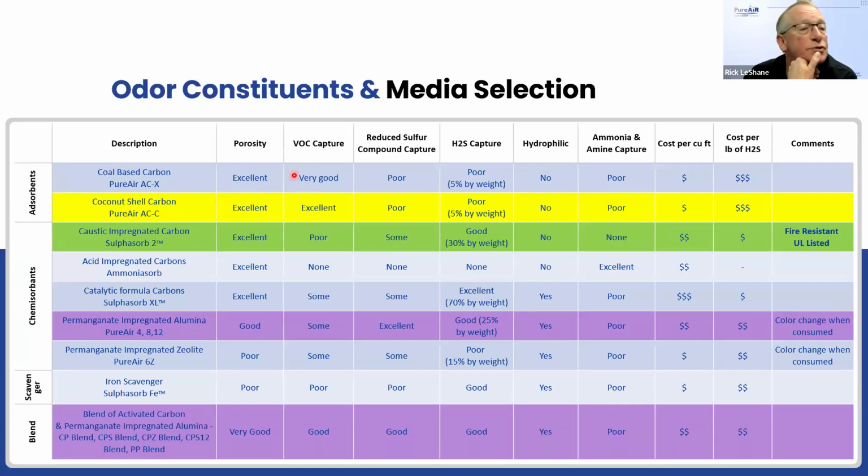A lot of times if you use just basic activated carbon and you have a spike in temperature, which results in a spike in H2S, the incoming molecules of H2S or odor will push out the molecules already in the activated carbon, and you'll end up with an odor breakthrough, which no city or county or municipality wants to happen. A lot of times they end up making the newspaper when they get odor breakthrough, and nobody likes that.